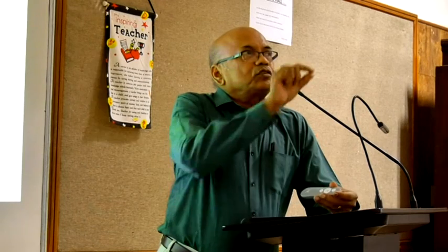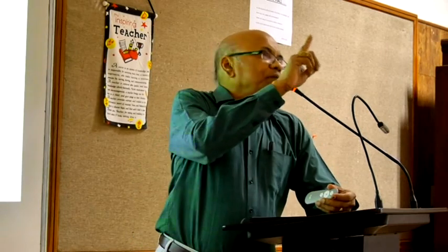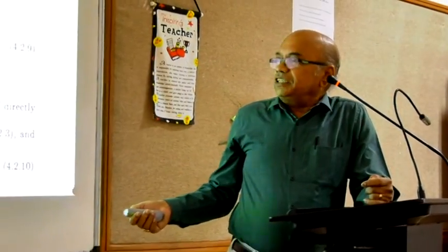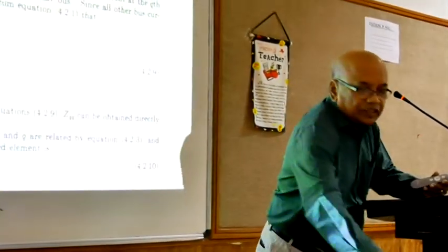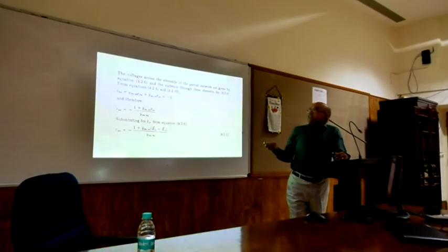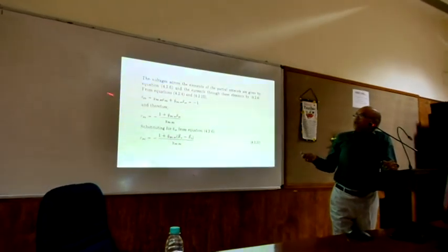IPQ is the current through the PQ branch, and in the Q, the current IQ equal to 1 per unit is injected, and therefore you have IPQ plus IQ equal to 0, or IPQ equal to minus IQ, that is equal to minus 1.